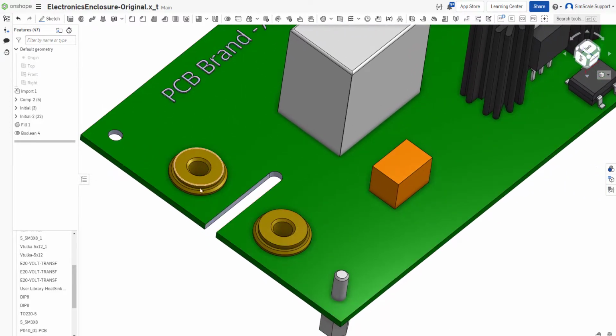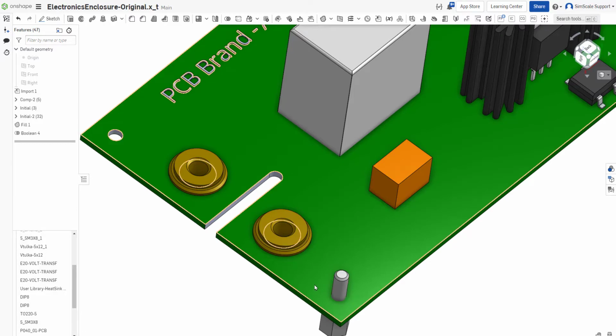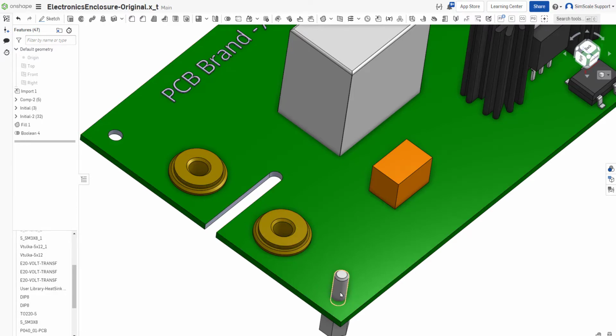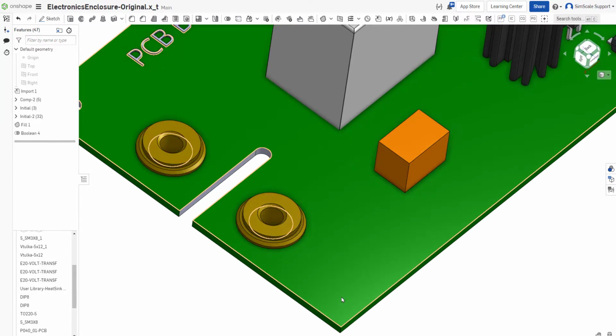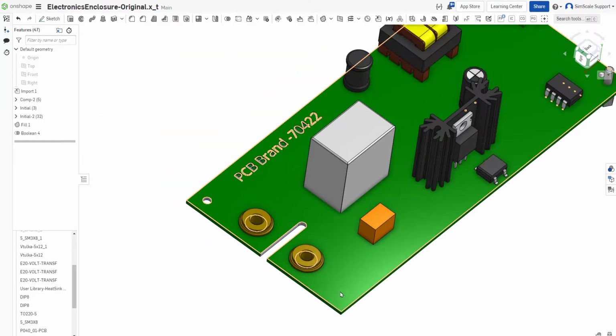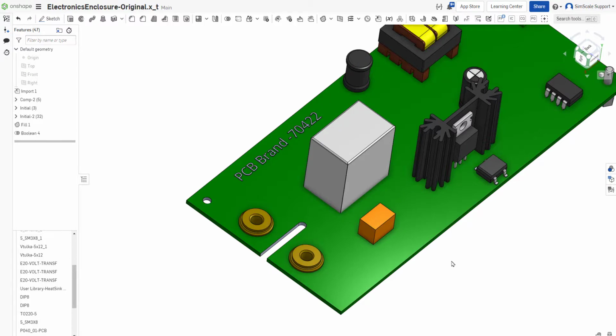If you check the other connecting pin which is interfering with the PCB, when you hide it, you might not see the hole on the PCB. This means these two entities are overlapping. So the Boolean operation should be done for all the connecting pins.